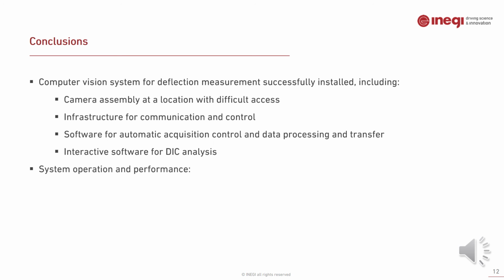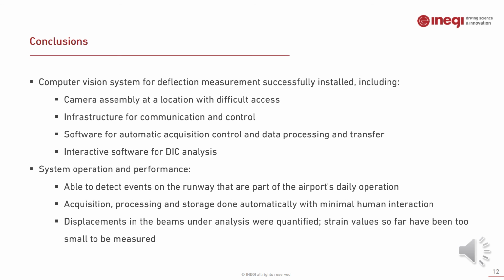As for the system's operation and performance, we were able to detect events on the runway that are part of the airport's daily operation, and not only landings but also takeoffs and taxi operations. We were able to develop a tool that acquires, processes and stores all the data automatically with minimal human interaction, and we were able to quantify the displacement in the beams under analysis, whereas strain values so far have been too small to be measured.